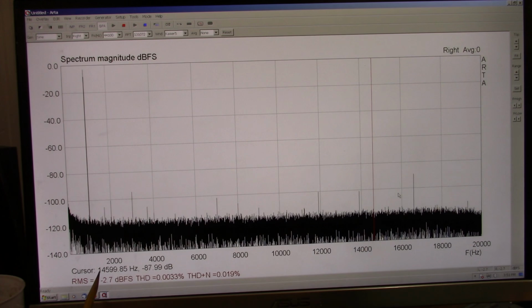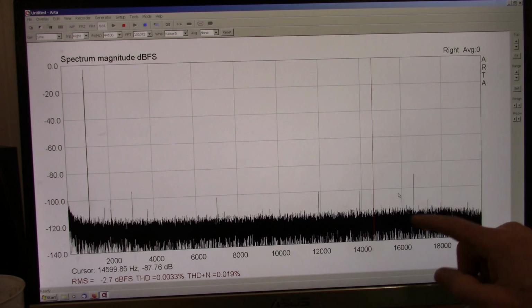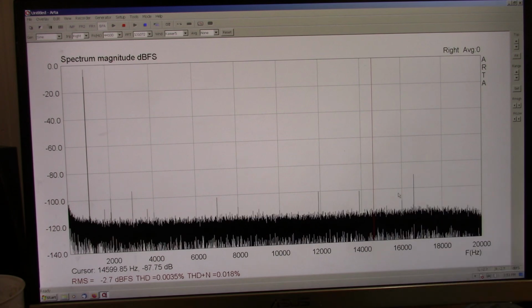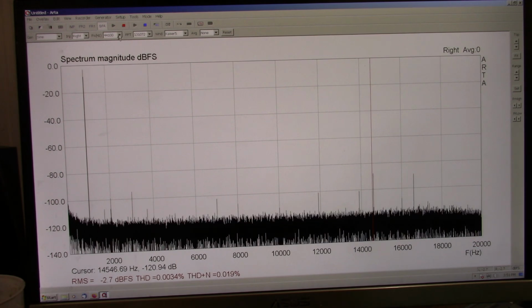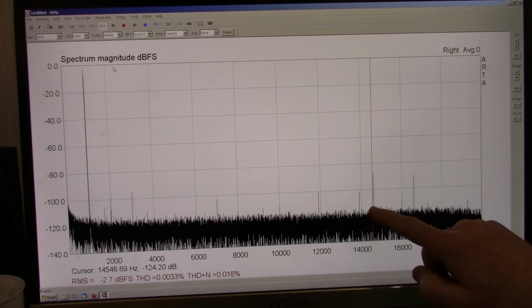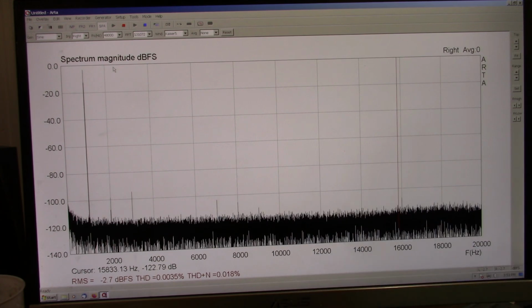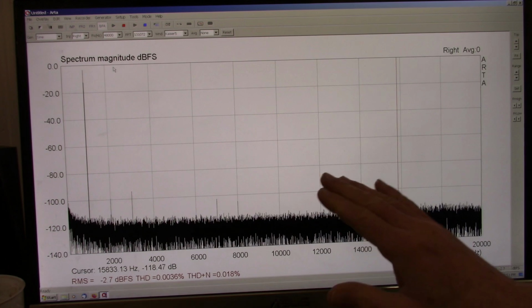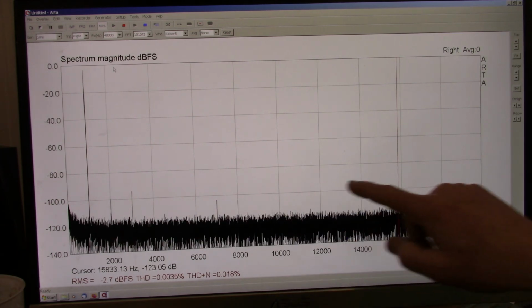87. You see it's at about 14,600. That's non-harmonically related. That's something to do with, I don't know, aliasing or digital capture of the signal. But when I use 4800, all this crap will be gone. See? Clean. So using 4800, I don't get any of those bogey data points there, those bogey peaks.